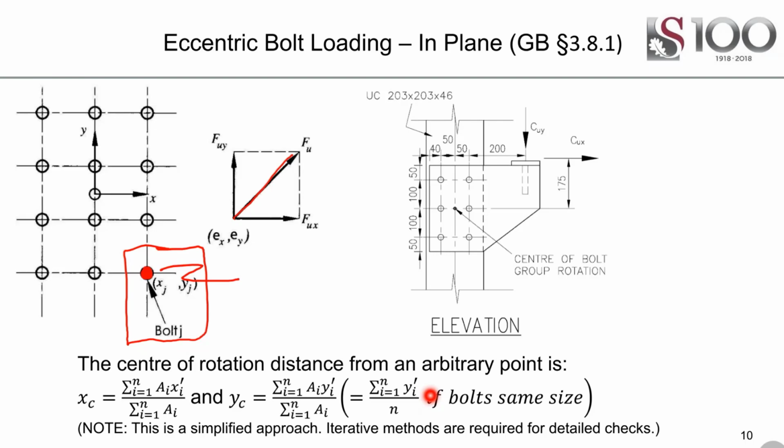When it comes to bolt J, we would need to firstly check what is the shear resistance, the bearing resistance, and then you can also have bearing resistance with edge pull out. I'll just call it A because of that edge distance. Now what you have there is that we choose the minimum of those shear or bearing resistances.